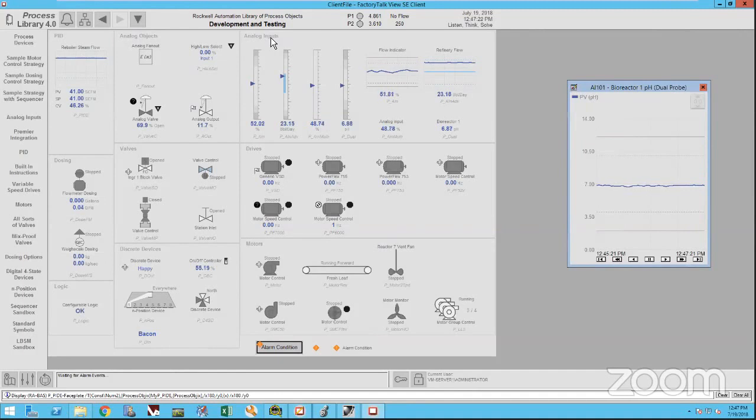And like I said, all the alarming settings are already standard. You can set it by default, and if we're using, again, that application code manager, you can set all of these defaults automatically. So once you set it in application code manager, you hit generate code, and all of that will be defined for you. You don't have to manually go in and do it. So the idea with all of these is that at commissioning, we don't require you to open up Studio 5000. The goal is for you not to have to do that. You should be able to do every configuration change that you need to from the HMI. Now, if you're still trigger happy like me, there's no reason why you can't open up Studio 5000.